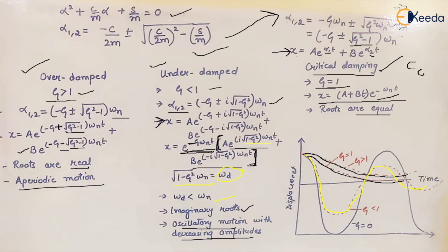If you close the door, it will oscillate. This oscillation can also affect the person who's standing on some side of the door. So this is not what we want. We want that it should stop, it should close in a very short duration of time, with the critical damping situation. Or we can also take the case of the cannon recoil or maybe the vehicle suspension system.